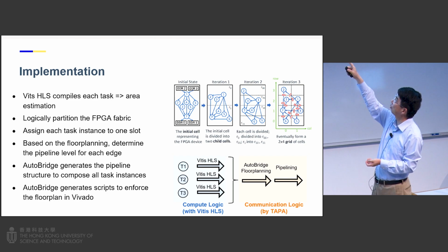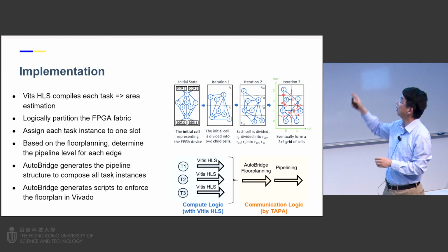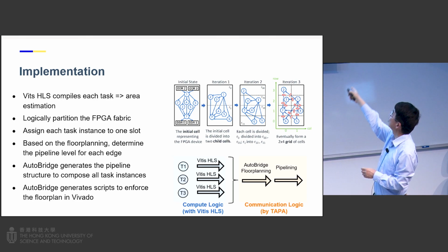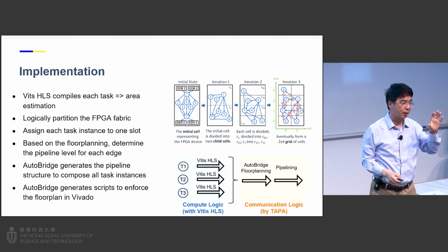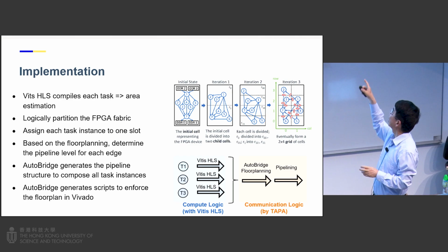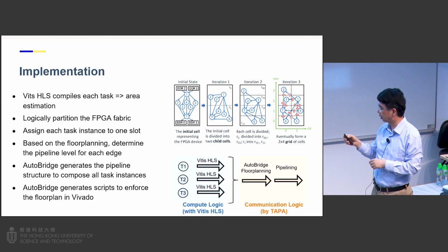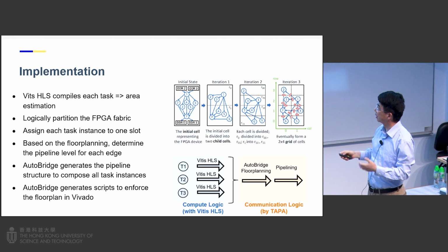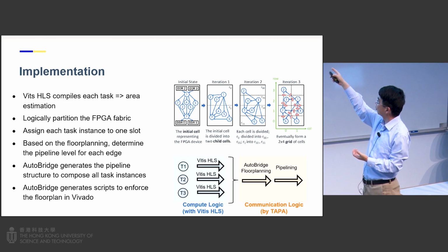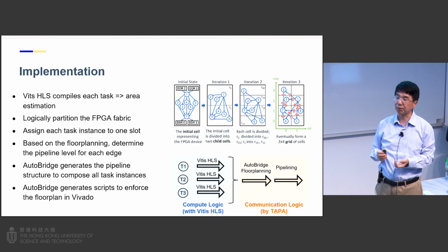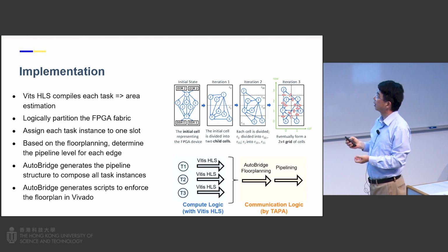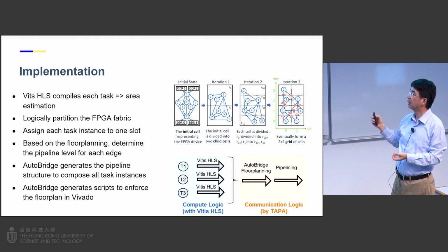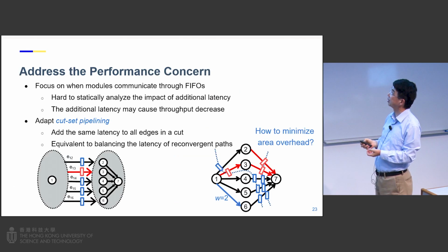You can see that you write your program as a number of modules, and then I will do, for example, iterative partitioning-based placement. I place them into regions. From these regions, I can estimate the delay from one region to another. Once I have that estimation, I can figure out how many cycles I want to add, and then I can do the necessary pipelining of the interconnect. So this is the idea called AutoBridge. I think this work got the best paper award at the 2021 FPGA Symposium.